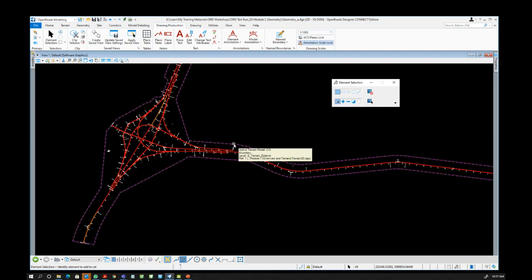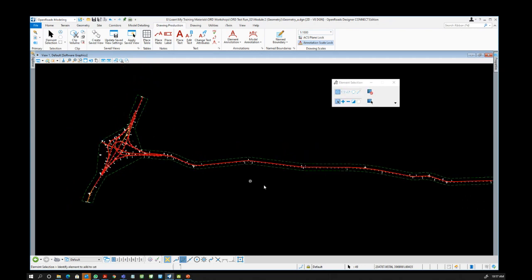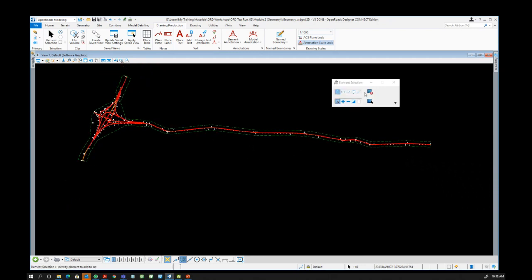Now, how about the vertical profile, the long section, longitudinal section or longitudinal profile? Where can I see that? Since this is coming from Civil 3D, LandXML, it already has your design profile or maybe existing profile, depending. So this is where the view tools come in. I want you to zoom into this location, where all these 8 toggles are located.